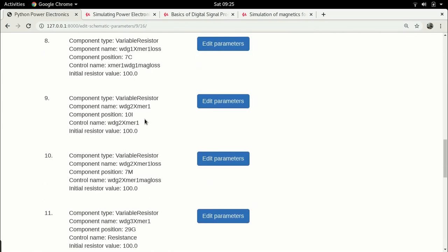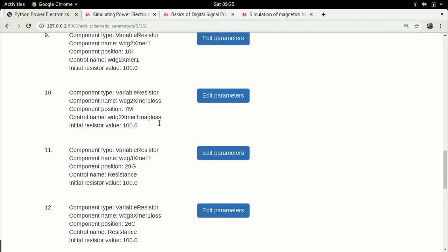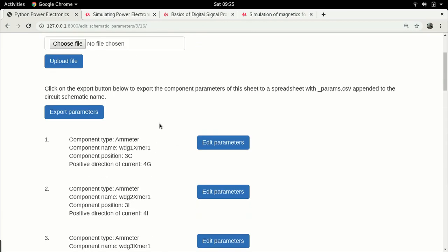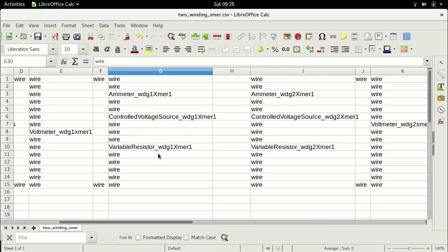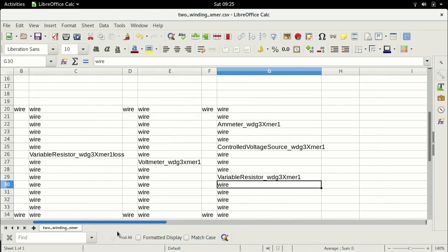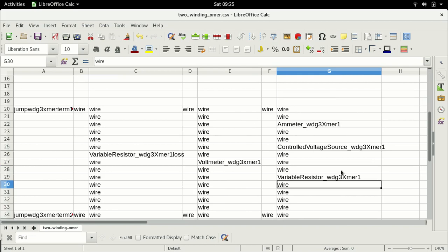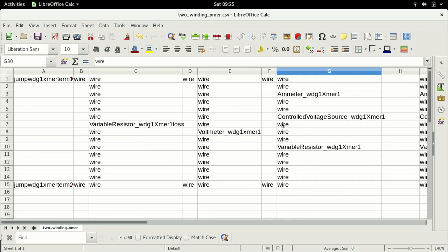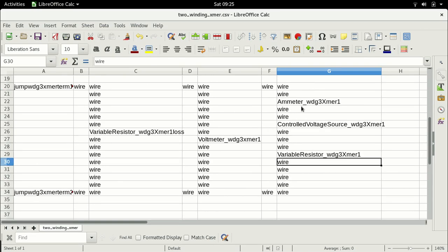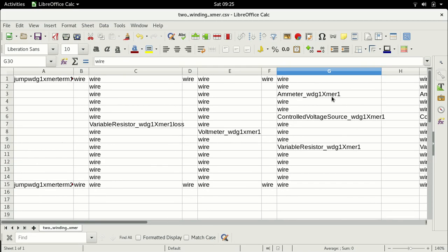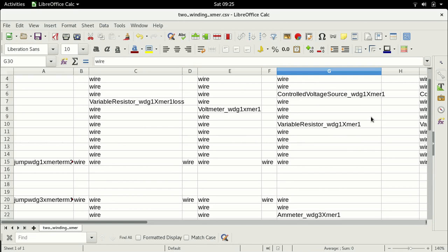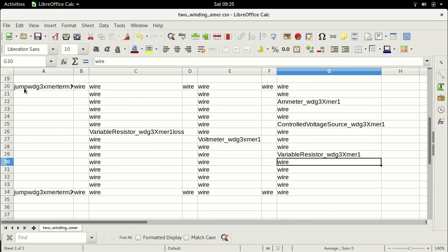And if we keep going, I think this way we have now come back to the normal transformer ratio of a forward converter, or the dot polarity. So we now have the dot polarity at the upper terminal for both the primary and the secondary. So now coming to the tertiary. What do we do with the tertiary? Now, as I said, the purpose of this tertiary is, when the switch is turned off, it has to be able to freewheel the energy stored in the magnetic field of the transformer back to the DC supply.